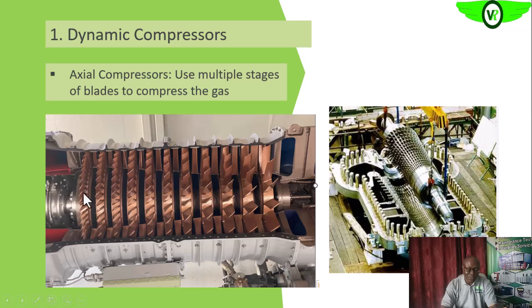So that gas molecule is accelerated by these sets of blades, and this acceleration is done towards the stationary blade. Okay, so here again, the stationary blade will serve to reduce the velocity that the incoming gas is already having, by virtue of the fact that the rotating blade is pushing it.